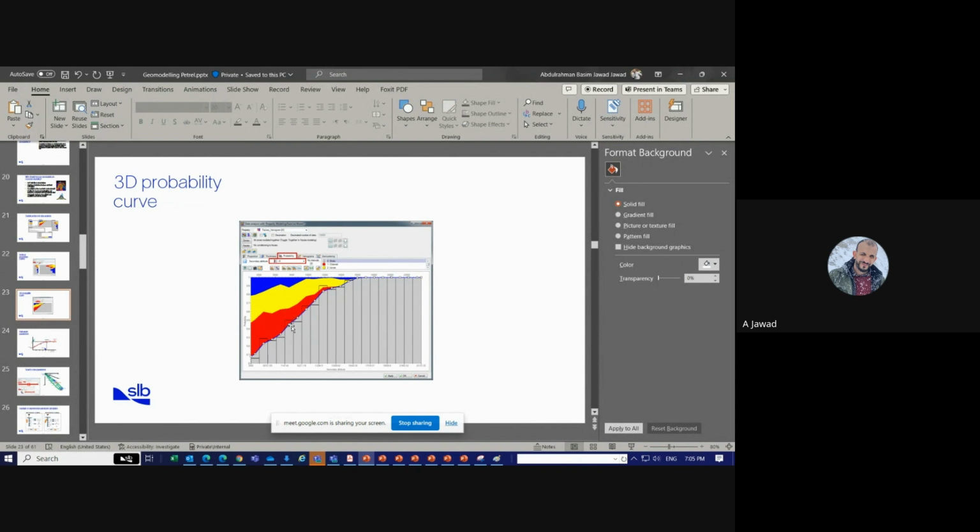So what the software will do is make a random selection between these realizations. It will convert it to a probability distribution curve, and then select randomly between them. For example, here, if we have 13,000 and the software selects a random point here, we will have high probability it is shale, but low probability it is levee. But here we have low probability of shale, maybe sand, maybe levee, maybe another channel. Because of these different probabilities, we need different realizations. The stochastic method will give you one map, maybe shale, another map maybe something else at this point between these two wells. And then you will measure uncertainty.